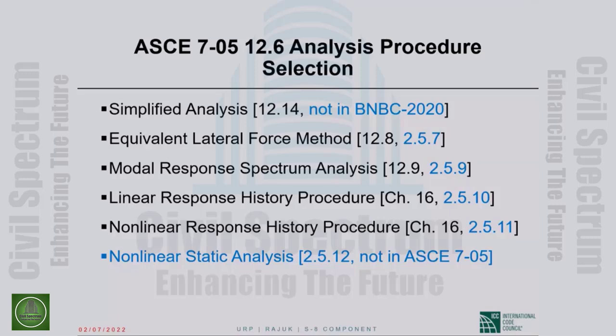Yeah. So response history analysis means that you subject the base of your structure to a history of ground accelerations. Ground acceleration as a function of time, so we feed pairs of acceleration and corresponding time. And these time increments have to be very small for us to get accurate results.